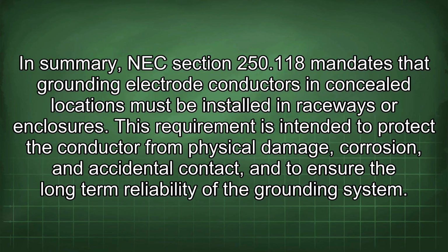In summary, NEC Section 250.118 mandates that grounding electrode conductors in concealed locations must be installed in raceways or enclosures. This requirement is intended to protect the conductor from physical damage, corrosion, and accidental contact, and to ensure the long-term reliability of the grounding system.